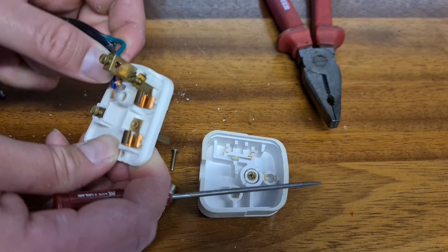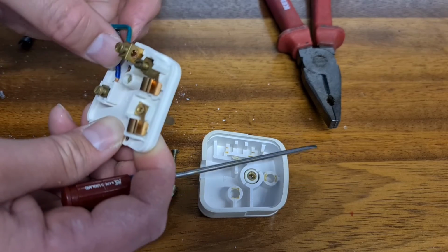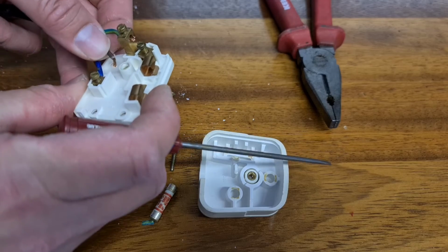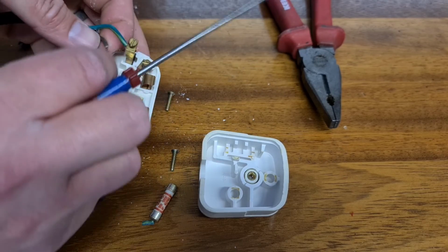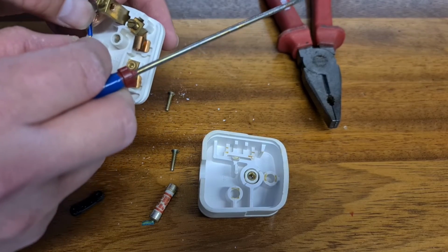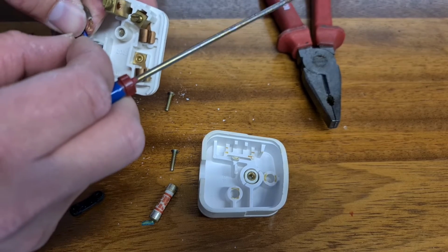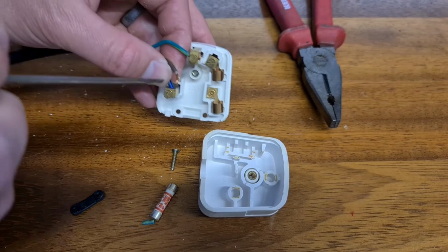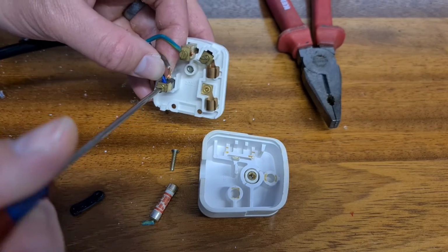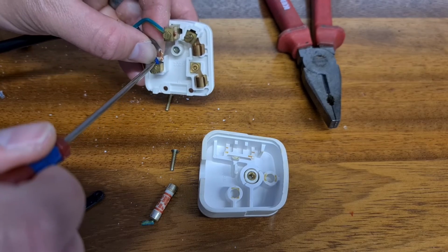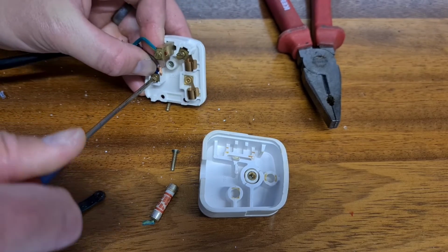The next one I'm going to do today is the neutral wire, which I'm going to place in just here. Now what you might find is that the green wire has to bend in order for you to get that wire in place. So let's get it in, and what I ideally want is all of the threads to go into that terminal. I want no loose threads inside my plug, and you can see it's completely clean there. I'm going to then tighten that one up there. Tighten it up.